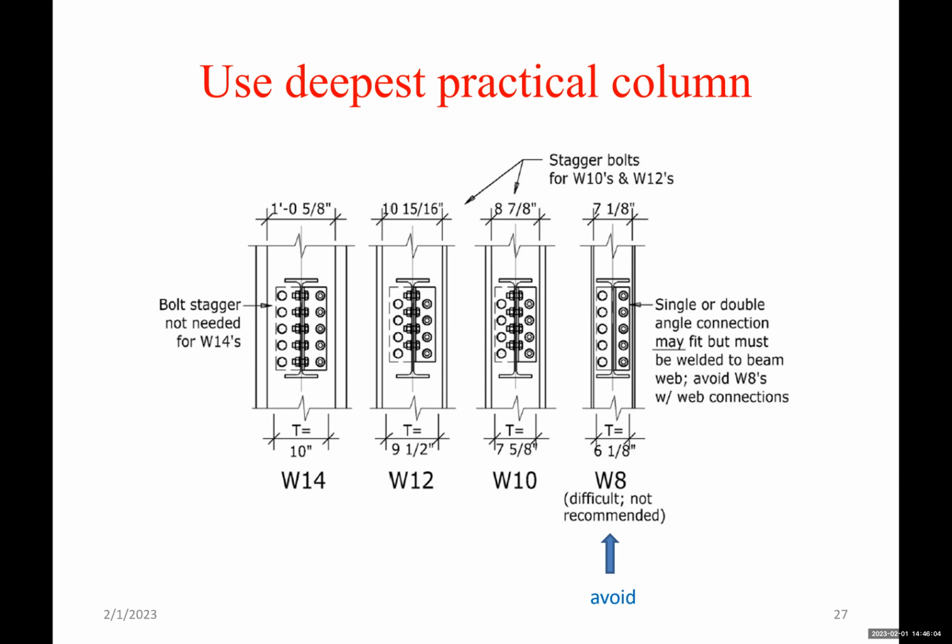This is one of the pieces of advice that I took as a young engineer, when I was designing this. I remember my boss told me at the time, do not use W8 beams. W10 is the minimum. And you can see now why it's true.